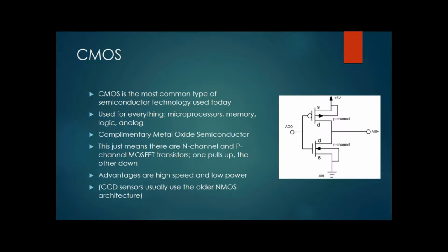So when you turn one on, the other one turns off, and when you turn the other one on, the first one turns off. So when they're just sitting there, sitting at 1 or 0, there's absolutely no current consumed. So it's very, very low power. It only consumes power when it's switching from 0 to 1 or 1 to 0.